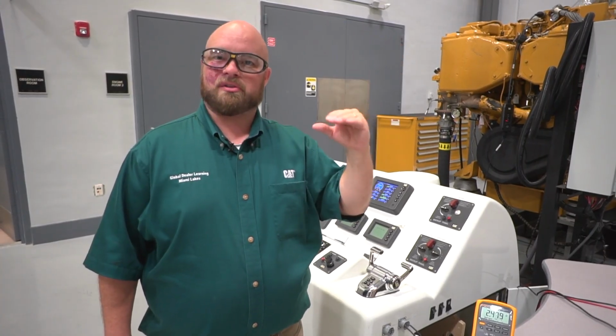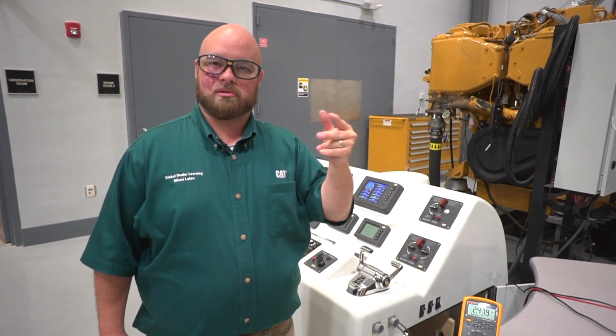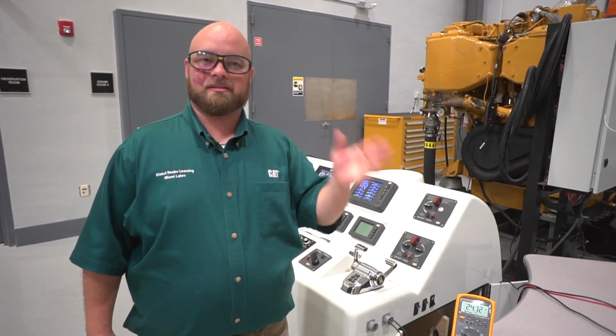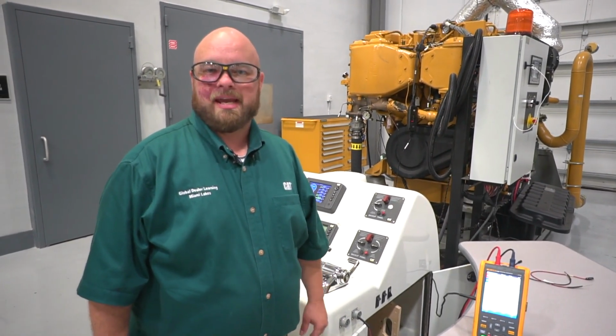And to understand what the chip is doing, it's constantly reading the differential between those two voltages and then determining the bit levels, either 1 or 0, taking all those 1s and 0s and then translating that into data. All right, so let's take a little deeper dive into looking at this CAN signal here.